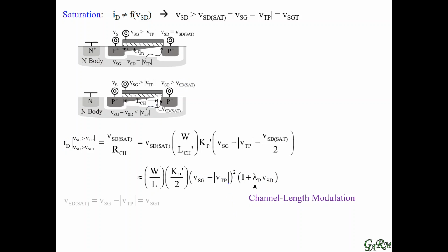In analog design, it's very useful to solve for the saturation voltage. And in analog design, we also often control what the current is. So we can take this term here and solve for it with respect to the current. So all we have to do is take the W over L and take it on to the other side.